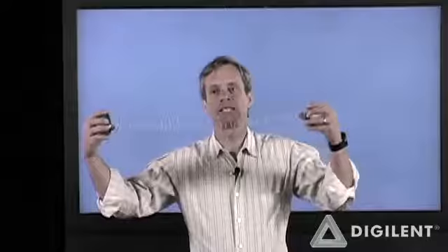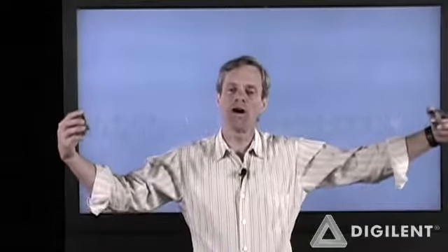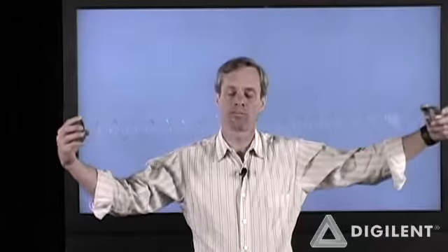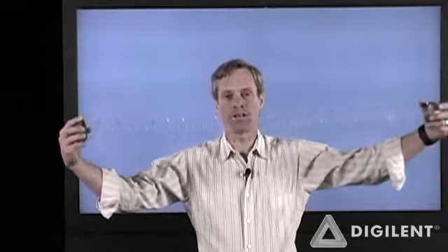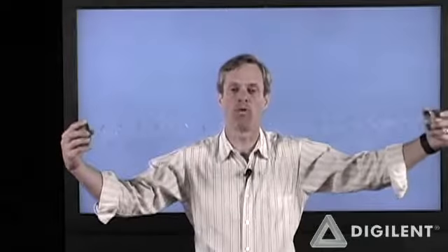My slinky can also have a nonlinear behavior. Hooke's law is a good way to model this system if the displacement is small. If, however, I displace this a lot, the more I stretch it, the harder and harder it gets to stretch the spring. In fact, in the extreme, after I stretch this far enough so that it's uncoiled all the coils and it's a straight wire, I would have to plastically deform the wire in order to continue to stretch it anymore. That would require a lot of force just to get a little bit of displacement.